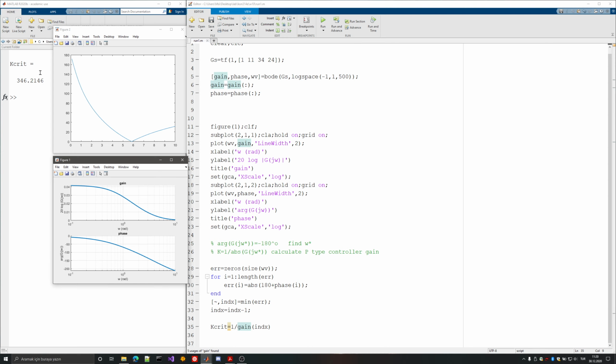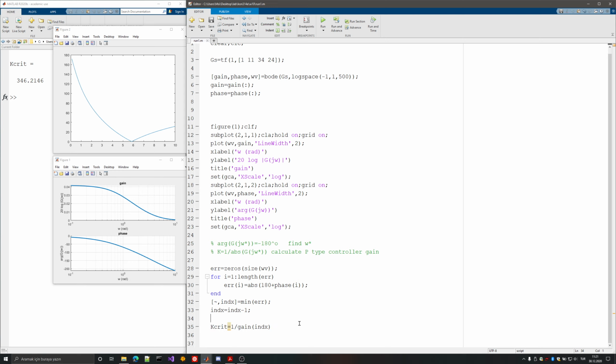So the graphic itself tells me now that this is the upper critical bound for the critical value. So I have basically the upper bound for the stability. Now, remember that this was the positive analysis. If you know root locus, you know that the positive root locus gives you the upper bound for that. And if you have a negative root locus, you can also get a bound from there, and it will be between those two values.